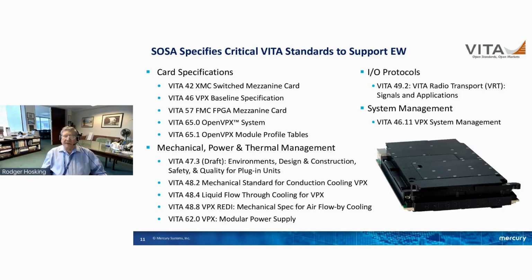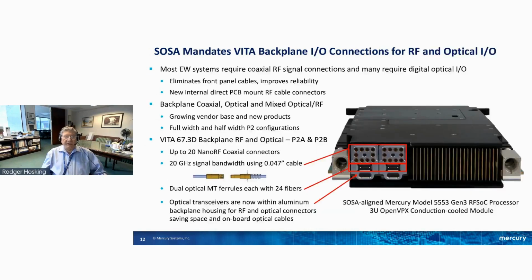SOSA specifies a lot of VITA standards, and here are just a listing of them. There's card specs, there's mechanical, power management, different I/O protocols, notably the VITA 49, which is a radio transport protocol for specifying packetization of signals, and system management, VITA 46.11. There's also new connections for the backplane.